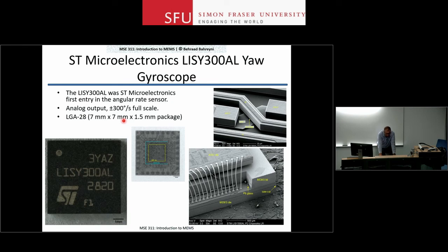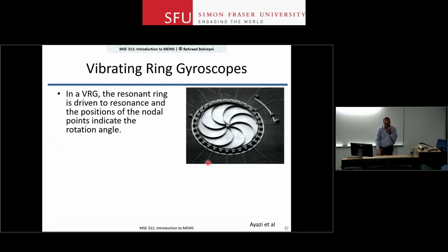And then, how we make these devices and how to save space. You can stack the chips on top of each other, so you can put your electronics right on top of the MEMS package and make the lateral dimensions a bit smaller. You can put them side by side as you've seen so far. Depending on where these companies feel most competent, they may use different approaches to fabrication here. This is an interesting device.